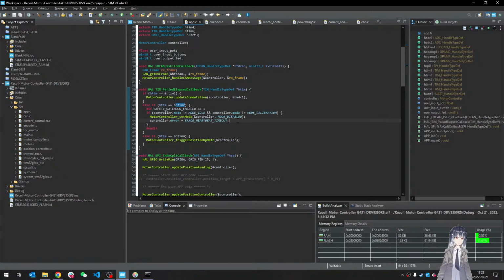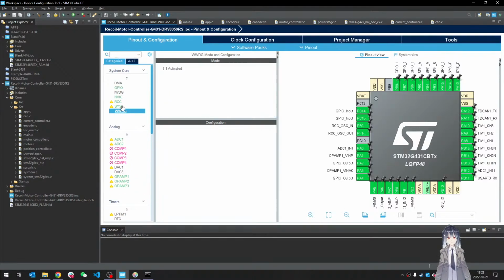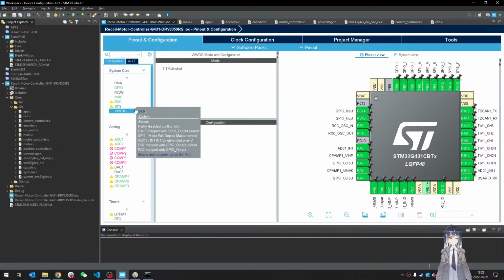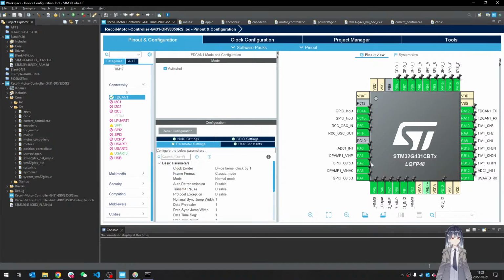Okay, so that's another scheduled event, basically a timer implementation of a watchdog, because ST has a watchdog, but it's software watchdog. The only way the watchdog can be functional is it will reset the entire device, and we don't want it to reset the entire device. Yep, that's the timer. And then finally we have FD CAN, or normal CAN. Basically it's the same. I'm configuring this FD CAN to be compatible with CAN 2.0, so it's basically normal CAN.